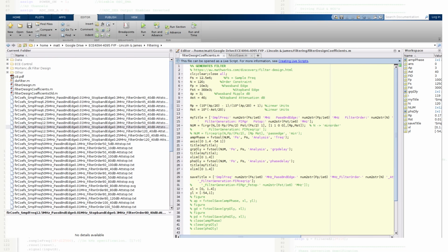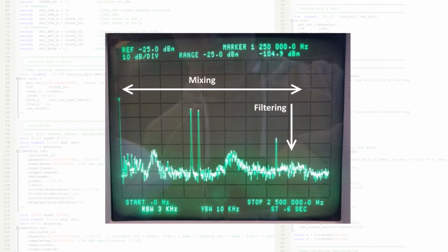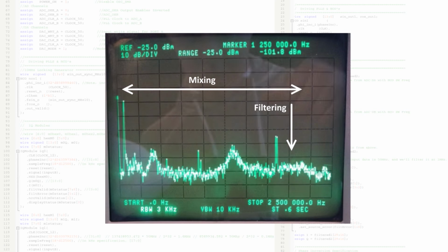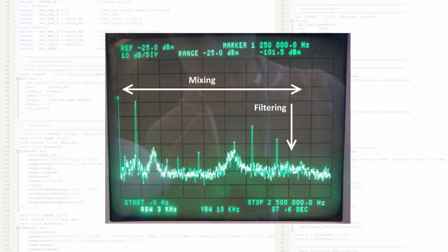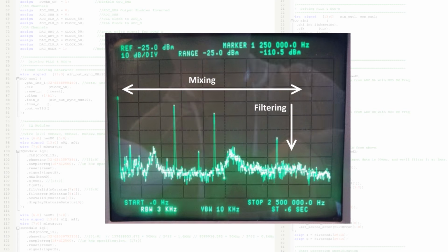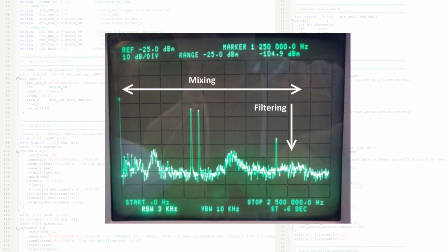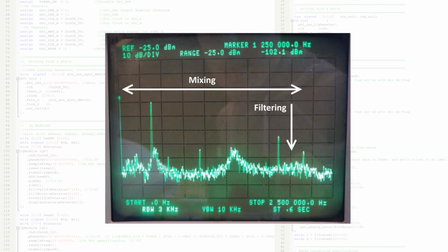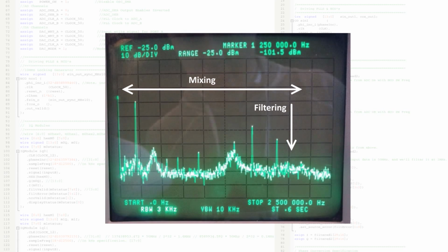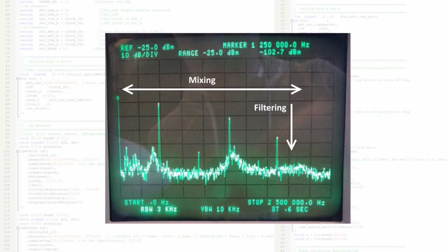We used the filter compilers in MATLAB to design our filter. In particular, we used the function firgr, which generates a generalized Remez FIR filter. This here is an example of one of our previous filter designs, but it wasn't sharp enough for our desired purposes. As you can see, as we slowly increase our numerically controlled oscillator frequency, splitting occurs, one that's plus and one that's minus from the carrier point. As the larger frequency increases, you can see it start to drop off and roll off with attenuation because of the filter that we've designed, whereas the frequency going towards DC becomes stronger and stronger as desired.